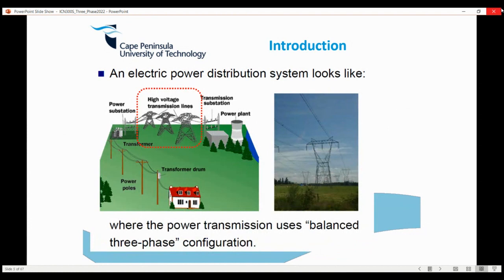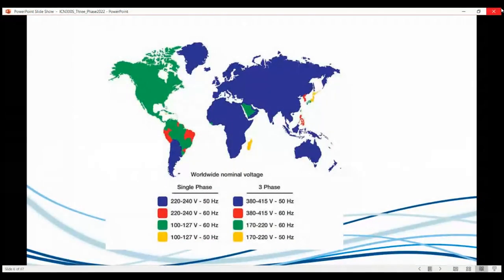Okay, so this is what a typical distribution system looks like. I could have probably gotten a better figure with values. I had it last semester. But anyway, you've got a power plant. You've got transformers stepping up voltages. They go through transmission lines, get stepped down with more transformers at the substation, and then there are also transformers on the poles, single phase transformers, which further step down the three-phase into single phase at the home. So that's the basic one. I'll talk about South Africa's one now, or arguably we have one, right, or there's load shedding.